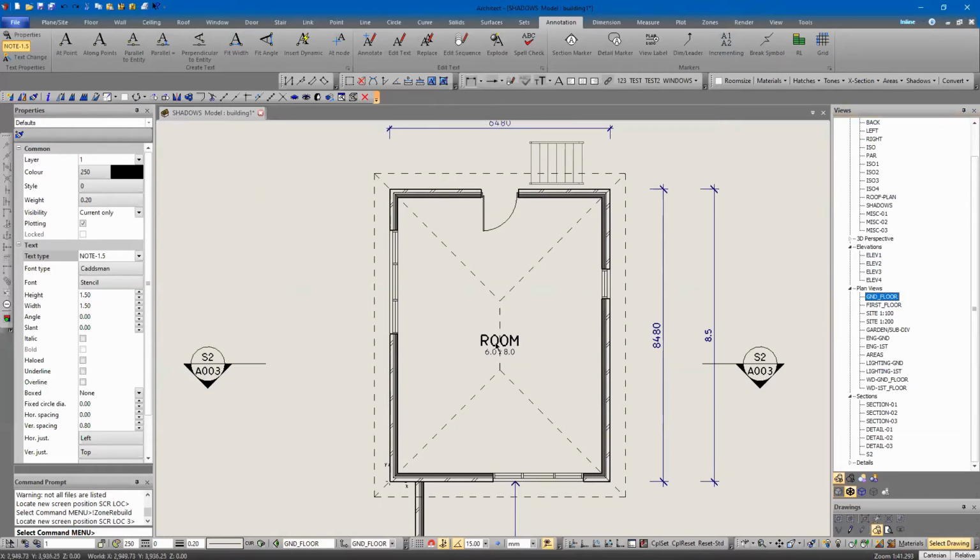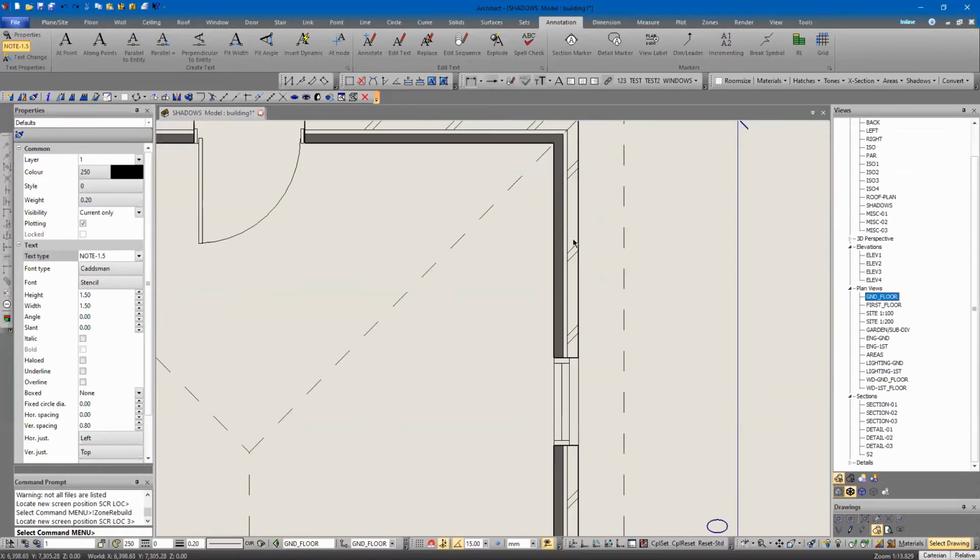Yeah, what happens also, because I always work like this and have my outside ply brick step down 170, 2 brick walls. Yep. So what you can't do that with the sketch walls or Yep, because they are. What I've done with the sketch wall is they're the exact same wall. Okay. What I've done is instead of using a cavity, I've actually used a material called air. And I make my cavity air with a black fill. Okay, so it is actually still 3 plies inside the hole, even with the sketch.